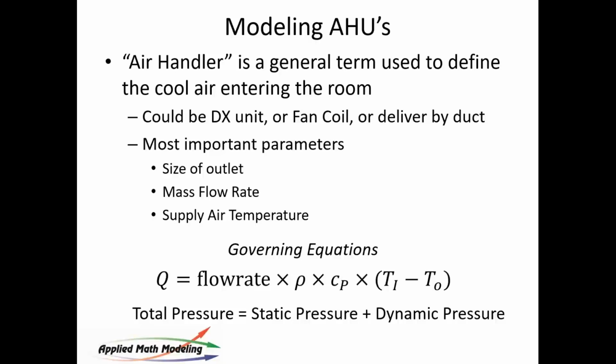This is something that, again, falls out of the Bernoulli equation for low-speed flows. Generally, we model these as incompressible because the pressures we're talking about here are very, very small in a data center. This is not a high-pressure situation, and it's not an aircraft engine or an internal combustion engine. We don't really have to worry about compressibility of the air. With that in mind, total pressure equals static pressure plus dynamic pressure.